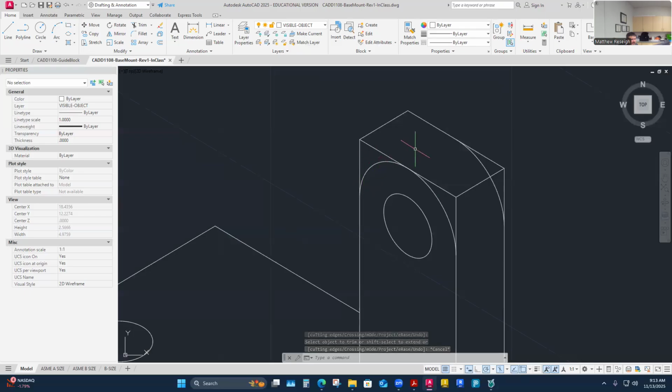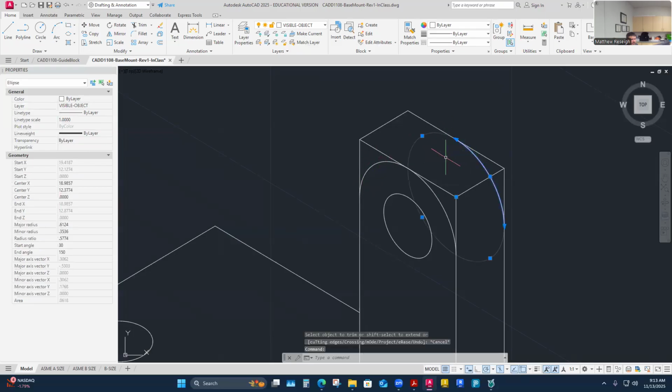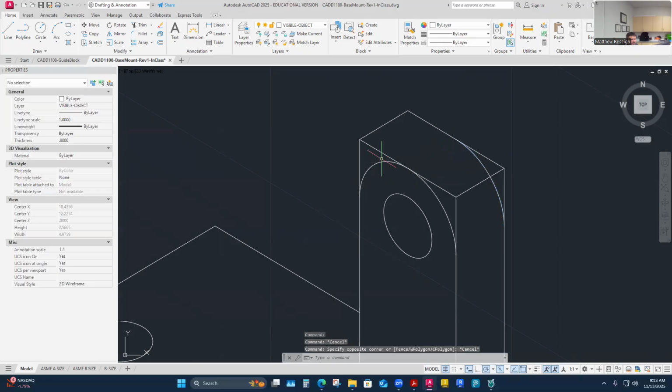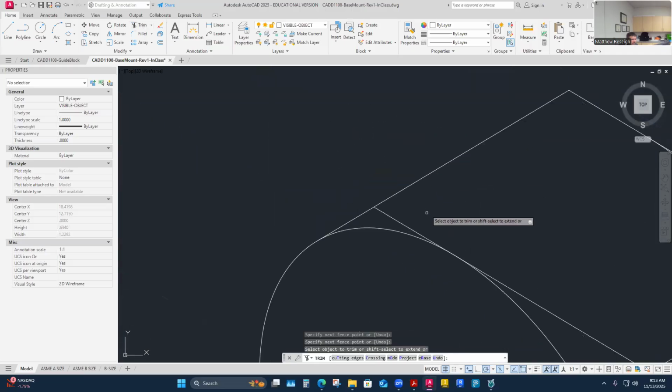This is going to carry across here where these two arcs end, or they meet this. Let me see what grips I have here. I think you have a few, but there's my quadrant again. It seems like that's what I'm going to grab and pull along that 30-degree projection plane there to there. I think so. Then if I trim this out, it should look correct.